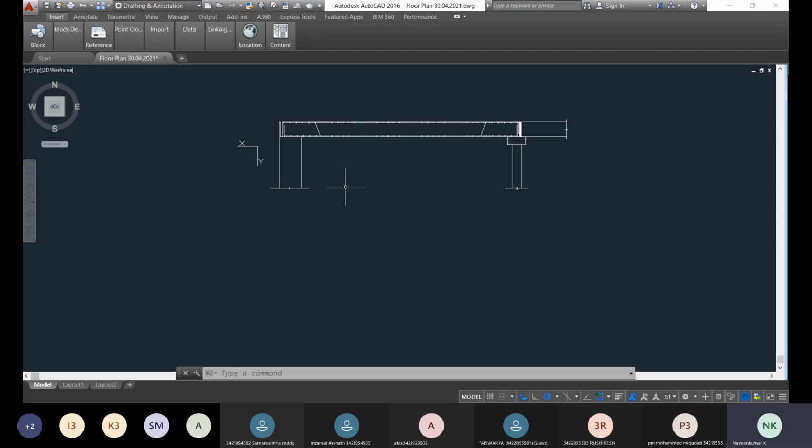In the middle, there are piers. Below the pier, what will be there? A pile type of foundation will be there, like a three-group pile or four-group pile, depending on the design. Above the pile, collectively for the group of piles, you will have one single column. That is called a pier.